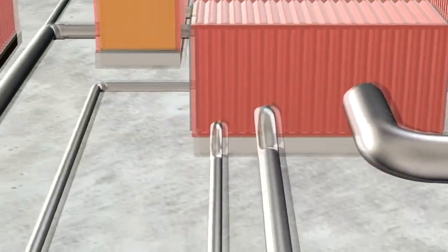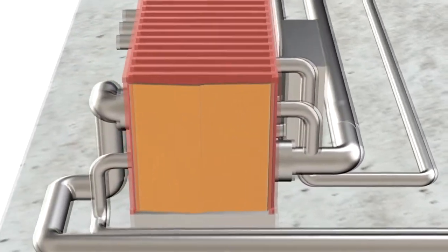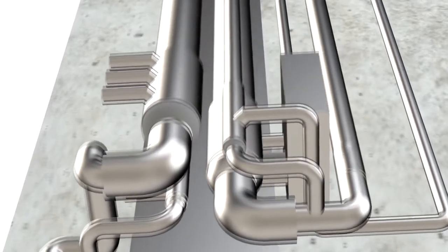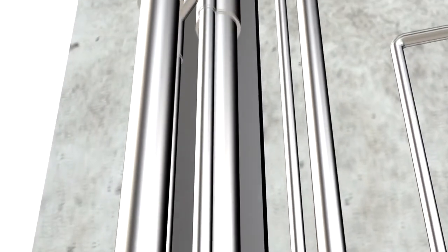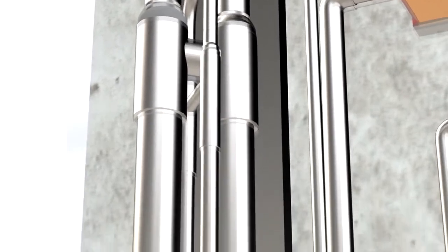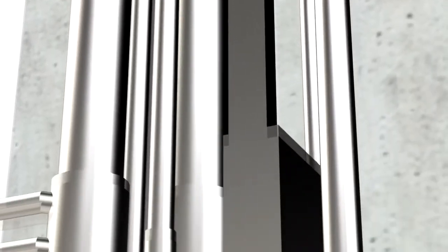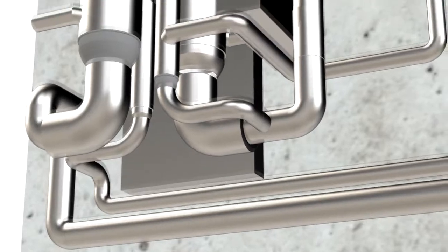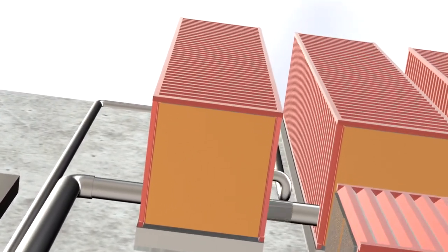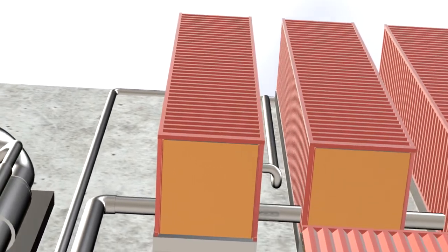After which our feed water goes through a series of pumps which pushes it through a sensible heat exchanger, which exchanges heat from the product that we produce, in this case brine and the distilled water, and the energy difference will be used to increase the efficiency of the system. After going through the sensible heat exchanger, there's a slight increase in temperature and it goes through the latent heat exchanger, which we'll now discuss further.